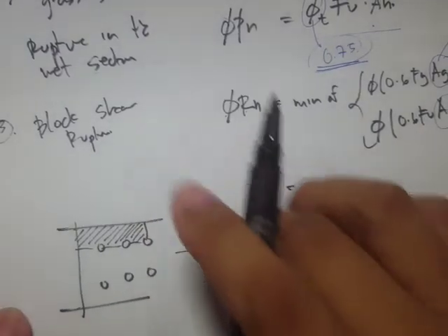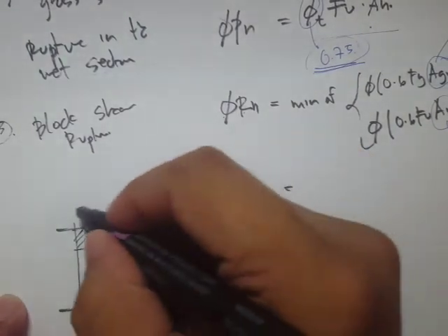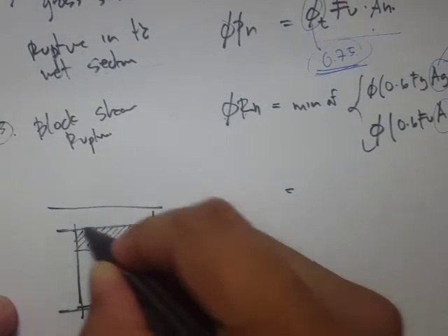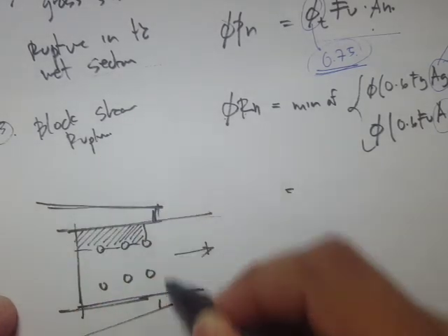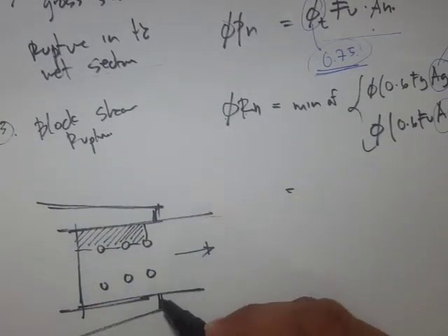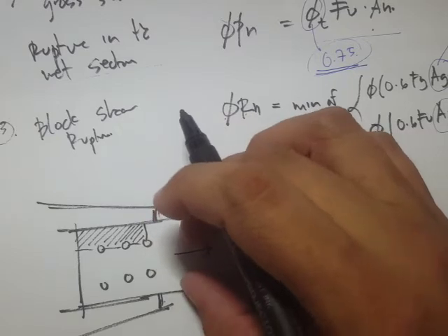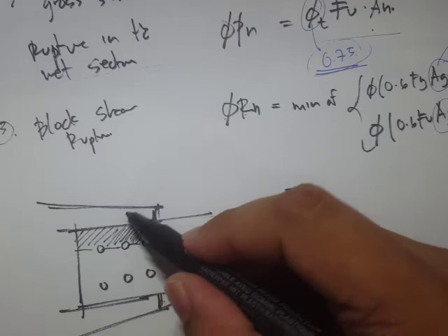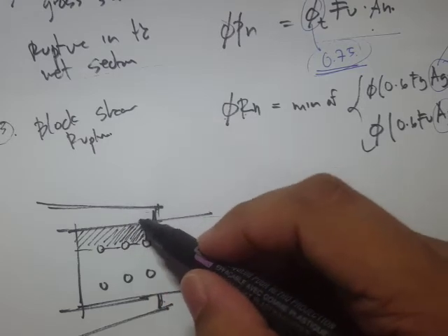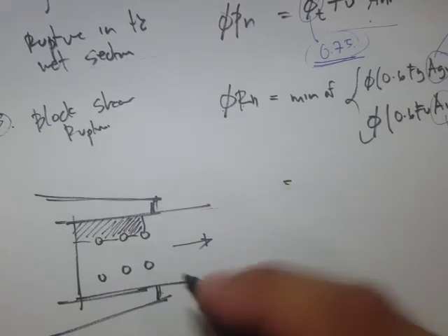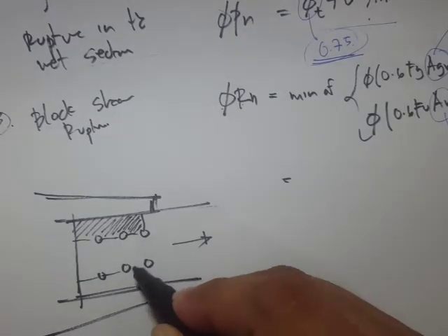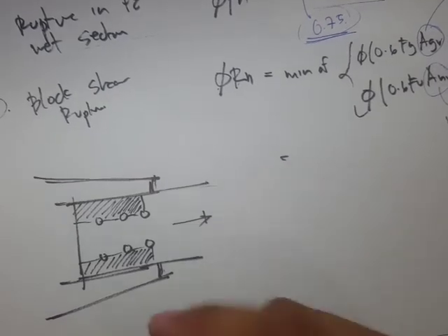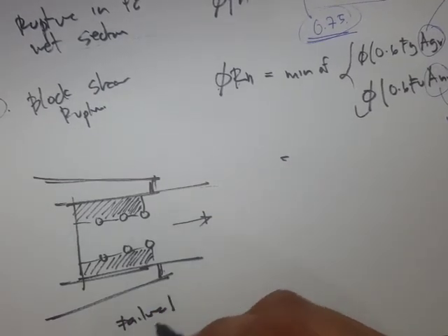So that's one. Let's say there's a gusset plate here, so you can imagine that there's something holding this member. When you're trying to pull this member, then this part is actually ripping off, and probably this part too. So that's one failure. Let's say this is failure 1.